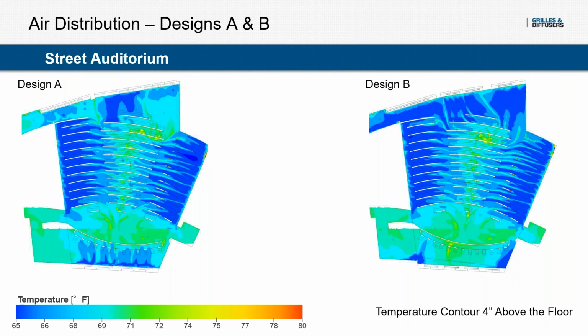But as you get to the center and towards the back, that air is a little bit warmer. This is not anything too much to be concerned about because we are supplying air from the back. It drives the point home that when you have a certain width, in this case about 65 feet across, with this specific type of loading, it is a good idea to have some extra supply from the back just to make sure that you get nice even air coverage.